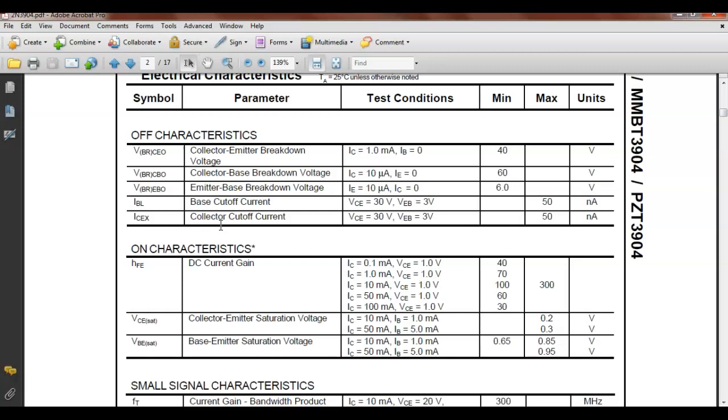So this is electrical characteristics. This is where the beta should be. HFE. Yeah. So this is what I was telling y'all last class. Even though books call it beta, in data sheets, normally it's going to be called hFE, which is the hybrid transfer ratio with the emitter common, what all that garbage stands for.